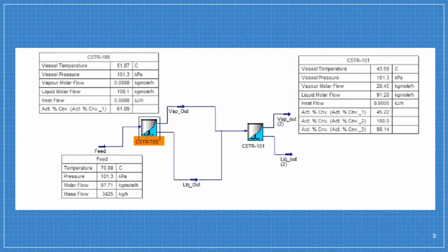This is the simulation diagram of the process conversion of the POME into biogas. There are 2 reactors used, which are CSTR1 and CSTR2. Firstly, the cellulose and water feed into the first reactor to produce glucose and hydrogen in the process of hydrolysis, and this glucose will convert into ethanol, carbon dioxide, and acetic acid in the process of acidogenesis, and the outlet composition of the first reactor will feed into the second reactor, in which the processes of acetogenesis and methanogenesis occur.